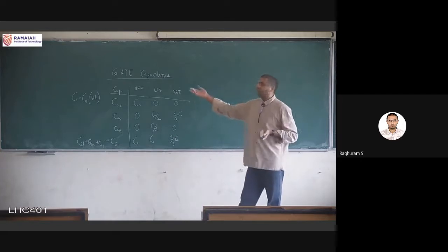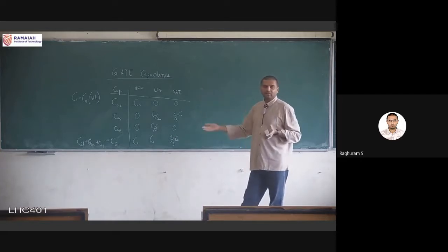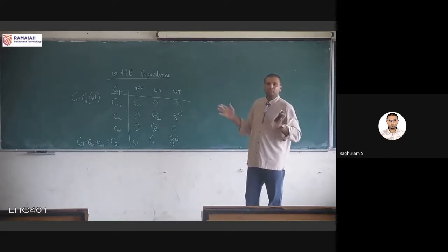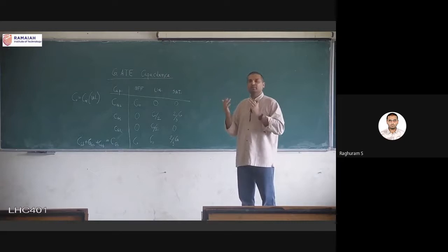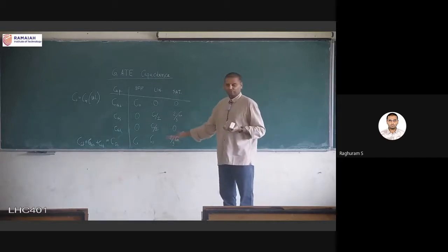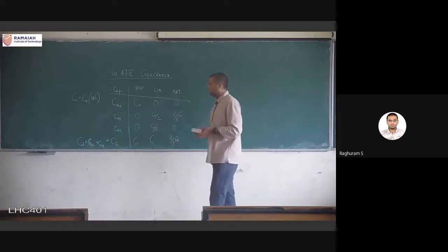You will not find these capacitances being fabricated anywhere. It is the gate terminal, the polysilicon, the oxide, the substrate. It has nothing to do with a capacitor, but because its nature is similar to a capacitor, it will have the same effect as a capacitance with these values. So this is the first component. The next component is our diffusion capacitance, which needs a slightly different analysis.